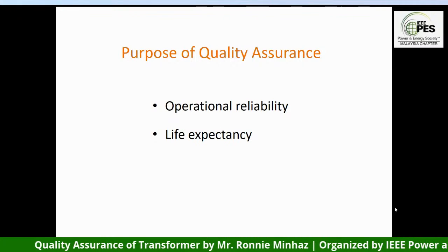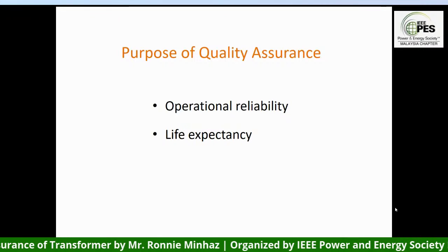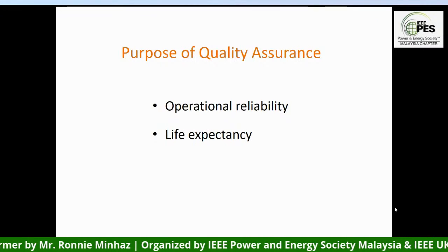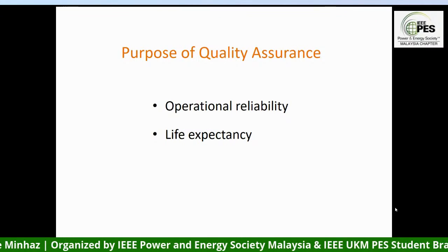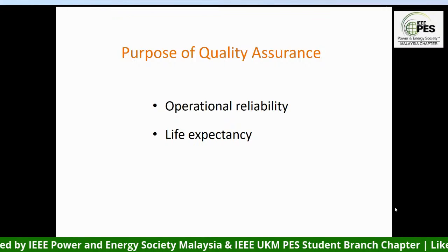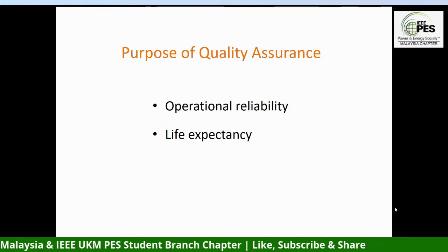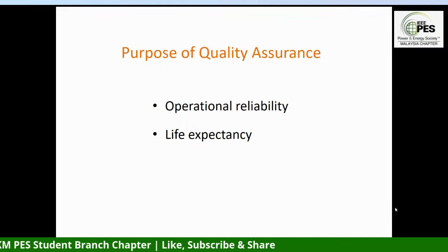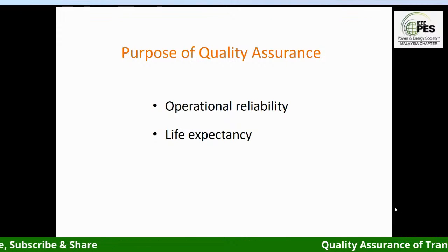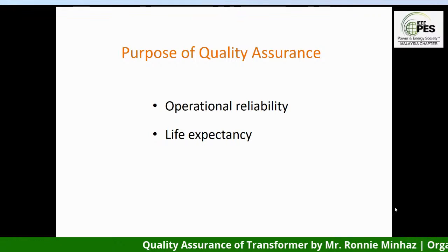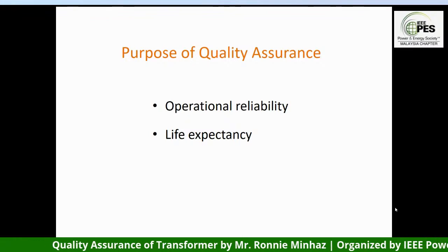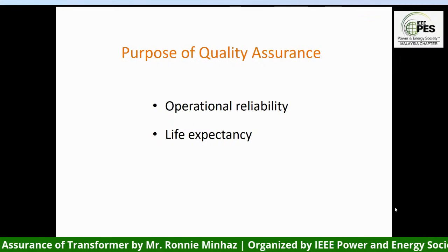Now, according to the IEEE guidelines, one of my colleagues at the IEEE Transformer Committee actually did an experiment. The result of this experiment was that if you procure a transformer and put it into service, and you do the loading at full load, and the temperatures are close to the limit, in that case, the life of the transformer would be 7 years.